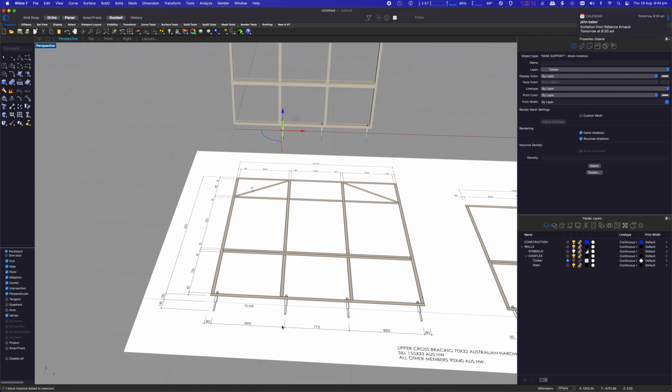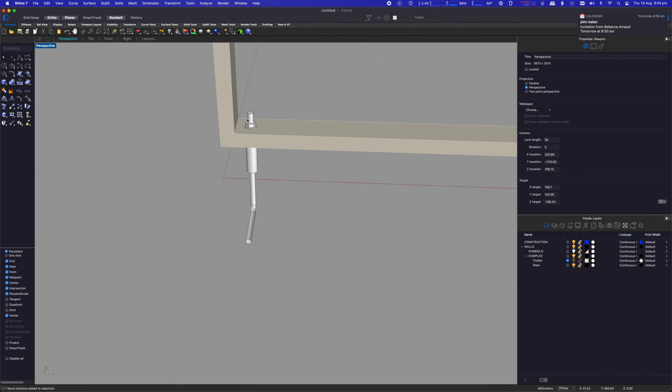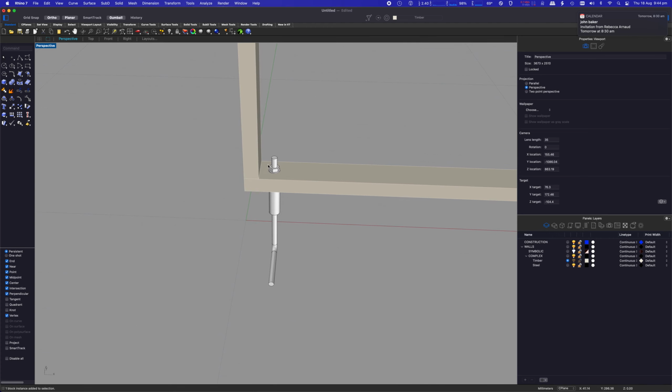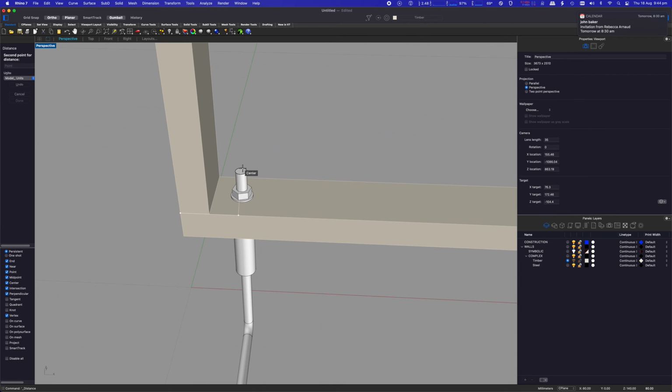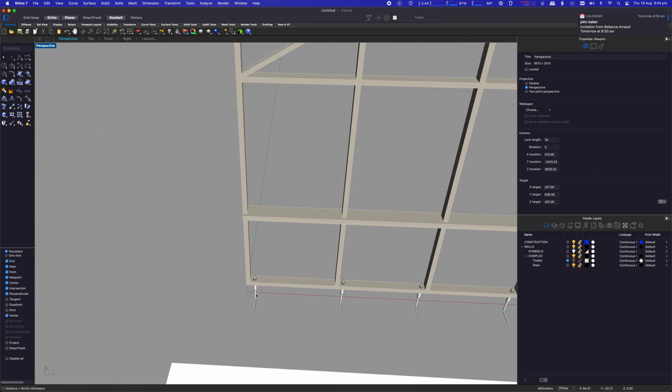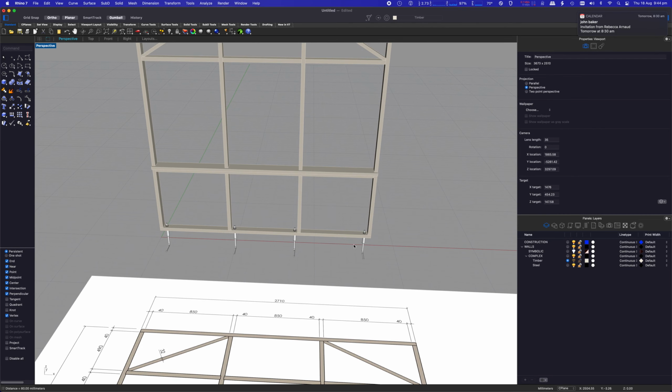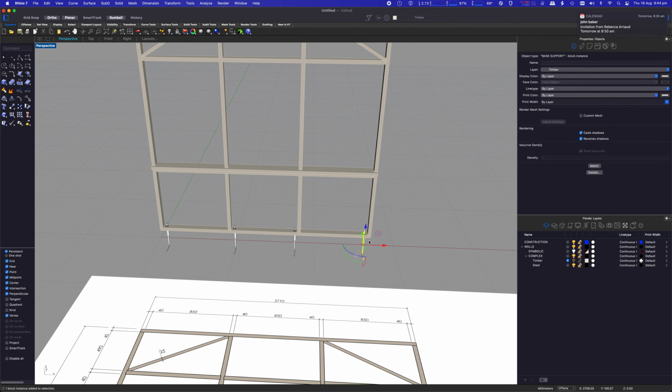And then there's another one that's 890, so click minus 890. And then just to check, the end of that should be 80 millimeters off the end of that. So let's go dim from there. I'm going to use my tab key again to lock it, and then I'm going to measure off the center of this, and look at that, it's 80 millimeters. So that all worked. Each one of those is a block.